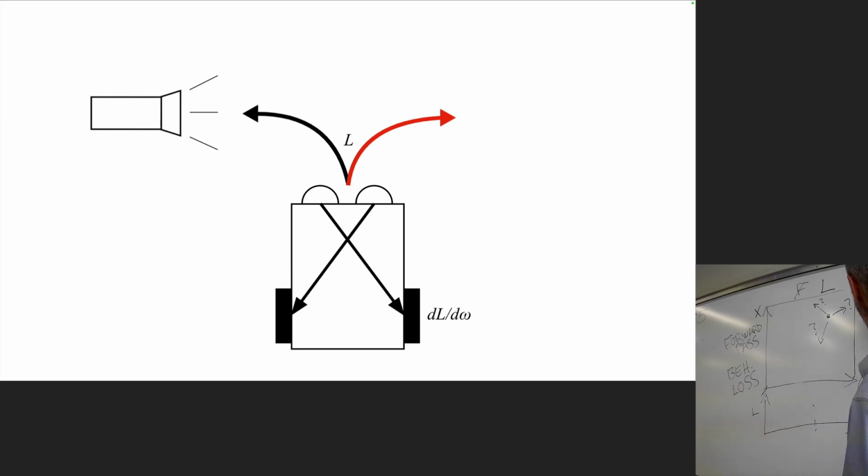And it just used F equals ma. This is velocity. We can turn velocity into acceleration. It knows the mass of the wheels. So the physics engine computed the forces that caused the robot to move in this direction and get this amount of loss. If we color in all of this material here, that's loss. It's a total number. So the physics engine knows L, it knows omega, and it has this equation. It knows how it calculated this.